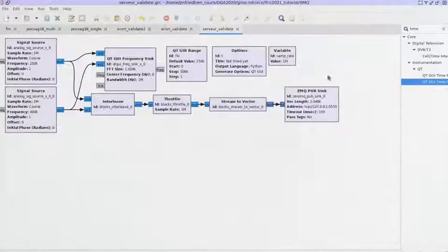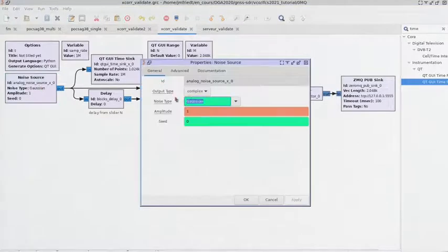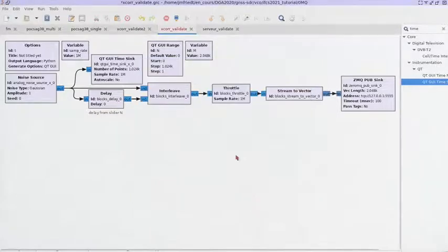So let us go back to GNU Radio. In this case, we see that we've replaced the same data stream, except that this time we have a noise source. A noise source with bandwidth B will allow us to find the time delay with a single beam width, because a noise only correlates at 0 time offset with a beam width of 1 over the bandwidth. And we will create what a radar would introduce, a time delayed copy.